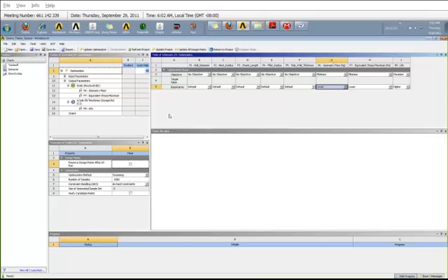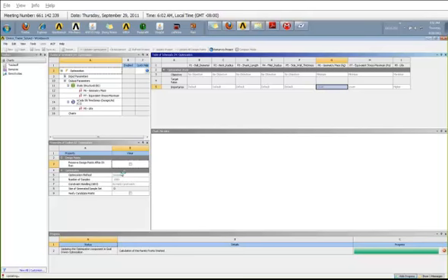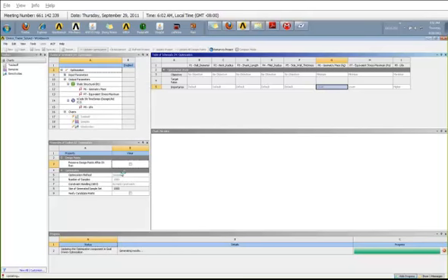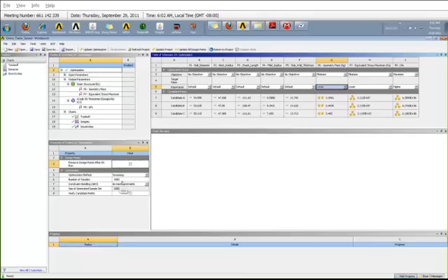Once this is set, I can hit update optimization. This is actually the basic default method, the screening method, as I'm showing you on the screen. It screens the response surface. It samples a number of points. In this case, it's 1,000 points, and it will sort out those 1,000 points based on the optimization criteria. Definitely, you can increase the number of samples that are generated.